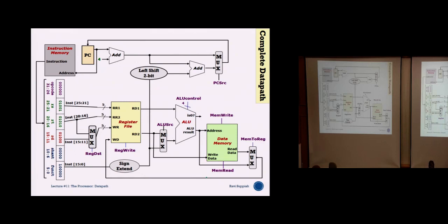Why do we ask this question? Because it's very easy to ask. The solution is usually to draw one line, that's 20 marks, wow, happy. If you don't know how to draw, that's it, gone. You can look at past papers, it's always the same. We will say that we modify the processor to do something new. And then what must you do? You must figure out where to draw the line to where, and do what. Most of the time it is modifying the multiplexer, adding some new hardware, and then maybe for this new instruction, I must take from this particular register, or take from here. So that's the usual pattern. As long as you understand how the instruction is being decoded and sent through the processor, you will know where you can tap this signal from.